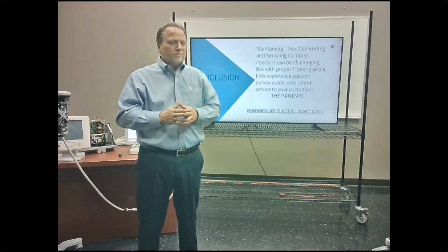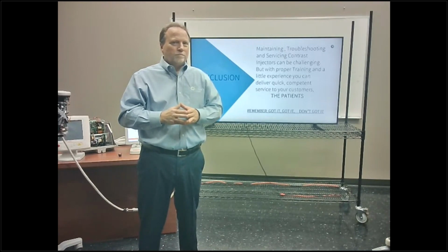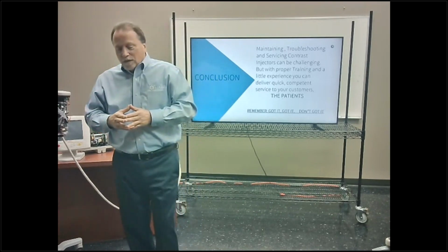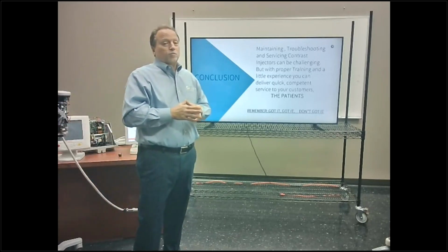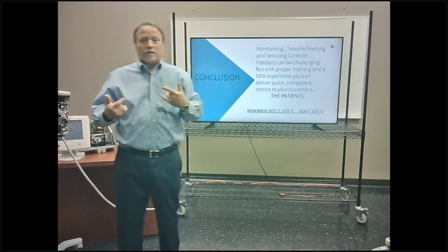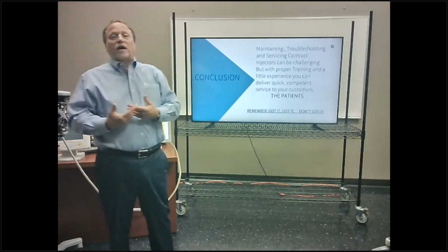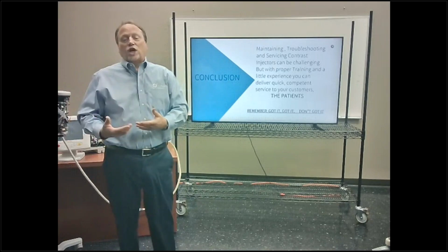All right, our next question is, how do you troubleshoot the Solaris EP injector when the injector head is in the MRI scan room? Good question. We don't. We actually disconnect the cables, bring the Solaris head out, and in the training kit that I provide, you have a service fiber optic cable. So all work is done outside the MRI scan room, and you can actually take that injector downstairs to your shop or wherever it's